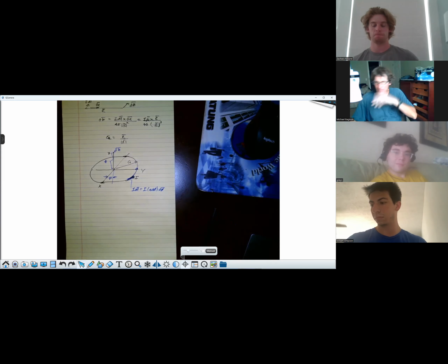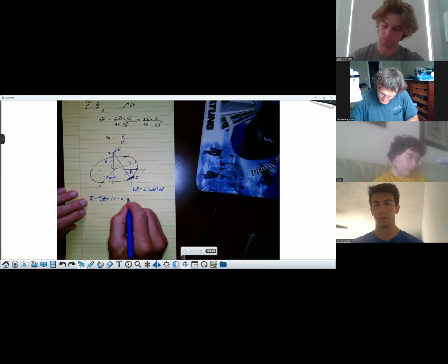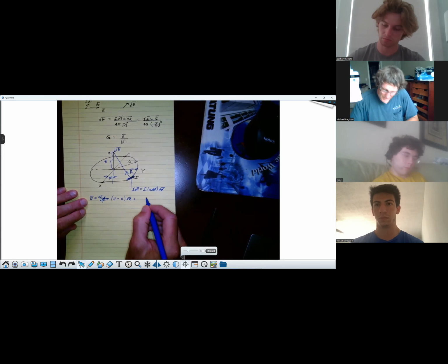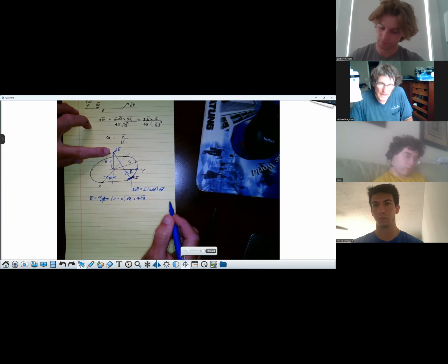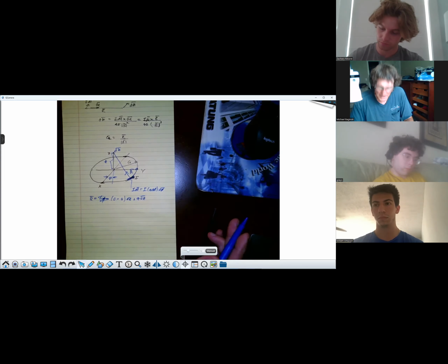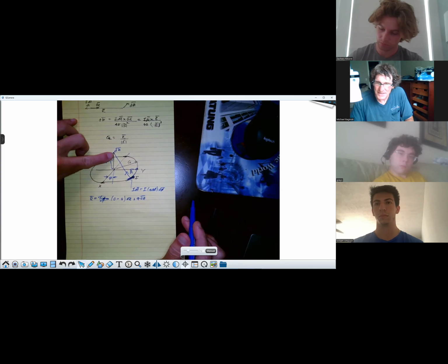It's 0 minus the radial distance here, which is a, and it's going to be in the a_rho direction, plus the z coordinate here is just z. The z coordinate here, in the xy plane, is 0. So it's z a_z. And here's where d phi loses meaning. If you're on the axis and you talk about what phi it is, it makes no sense. There is no phi. Y'all follow me?